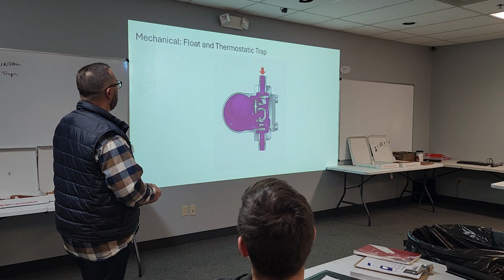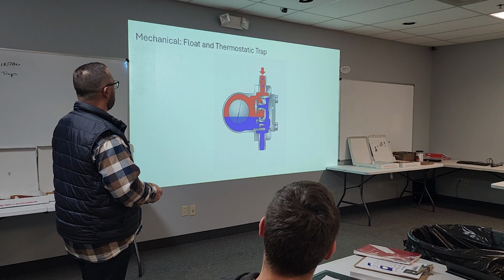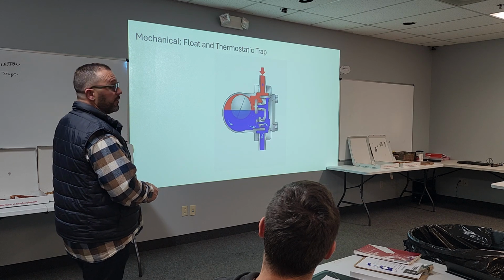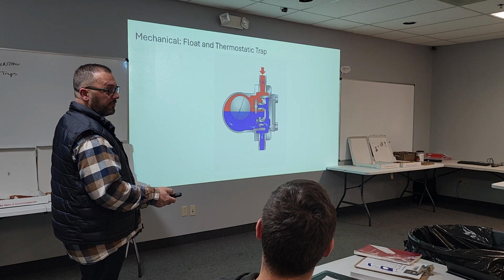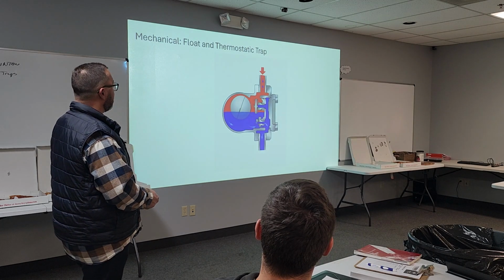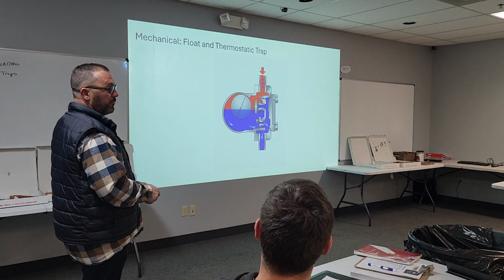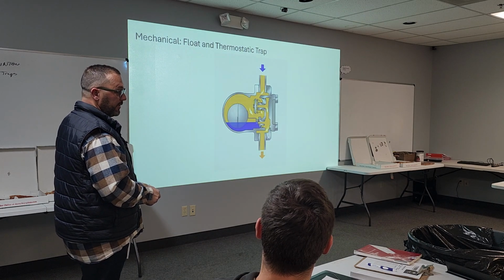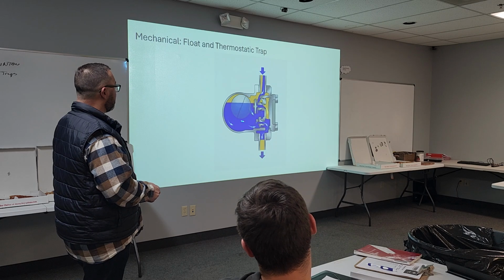That's where this bolt and this bolt come off, the cover comes off, and basically the whole guts of this mechanism go in there. It comes with a gasket for the cover. If you buy all those parts separately, it will cost you more to rebuild that than if you buy the trap module repair kit, which is a lot cheaper.